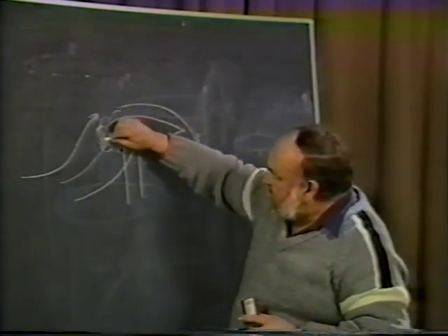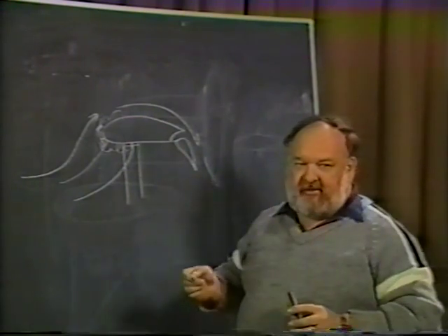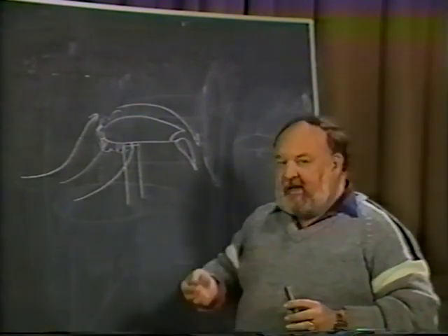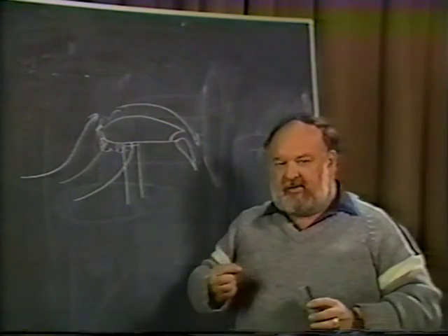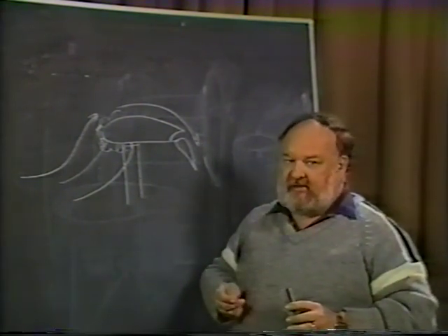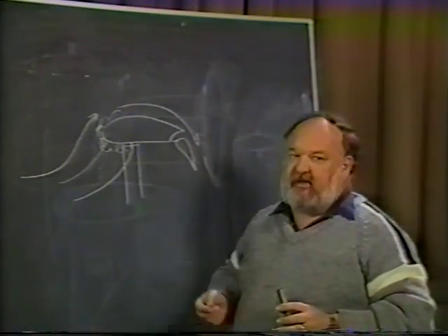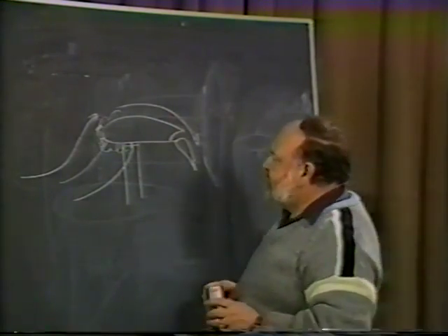Don't have a situation where you got skin and a big gap underneath there or some really heavy rivets or something like that. Even though it looks like it's under the wing and reasonably far back, it still might be a factor at high angles of attack and actually kicking off your stall pattern on here.